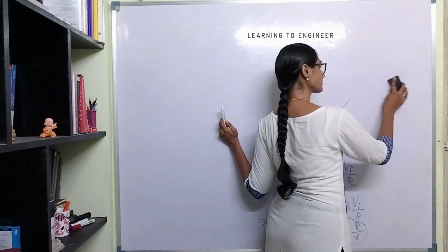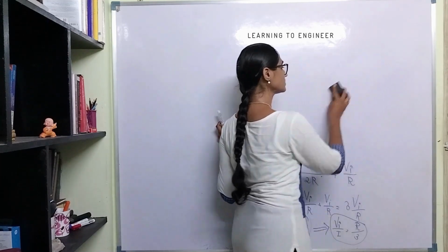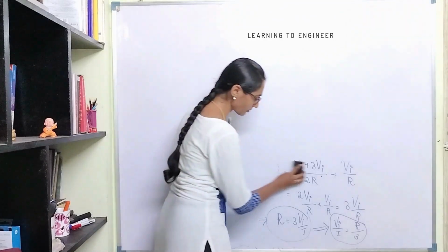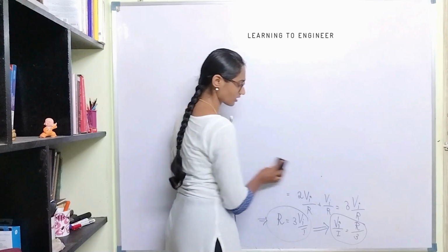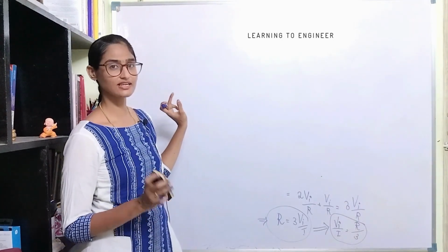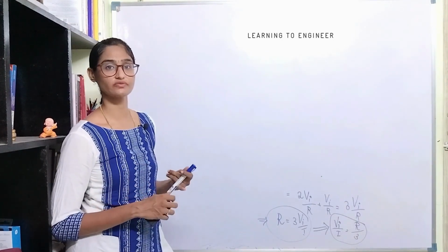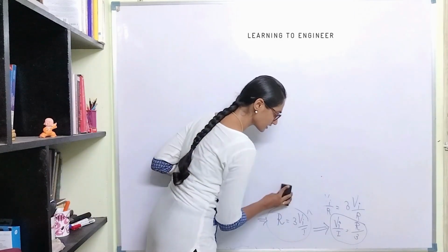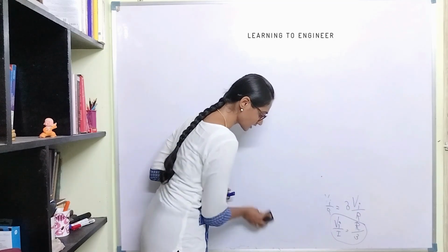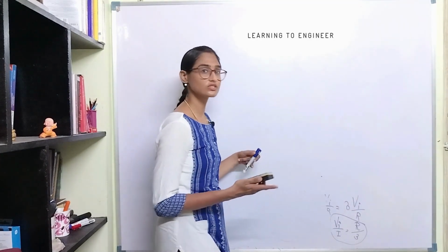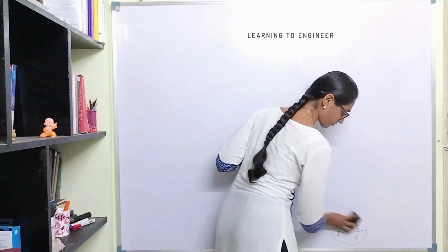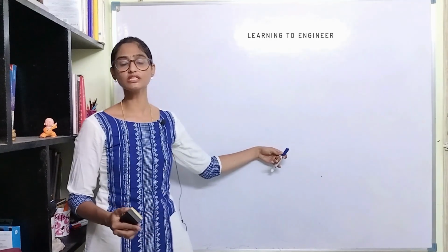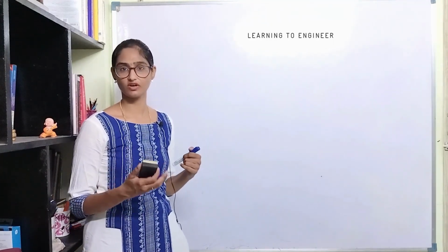Okay, so from the next video, we are going to see OPAMP as a non-ideal device. We are going to see the OPAMP as a practical guy, which is not ideal. So there will be slightly change in the concept of virtual ground. That is, we can't apply the concept of virtual ground anymore because there will be a small leakage current that is entering into the terminals of an op-amp. So it is not exactly zero as we did so far. So from the next videos of this playlist, we will be seeing the practical concepts of an op-amp.